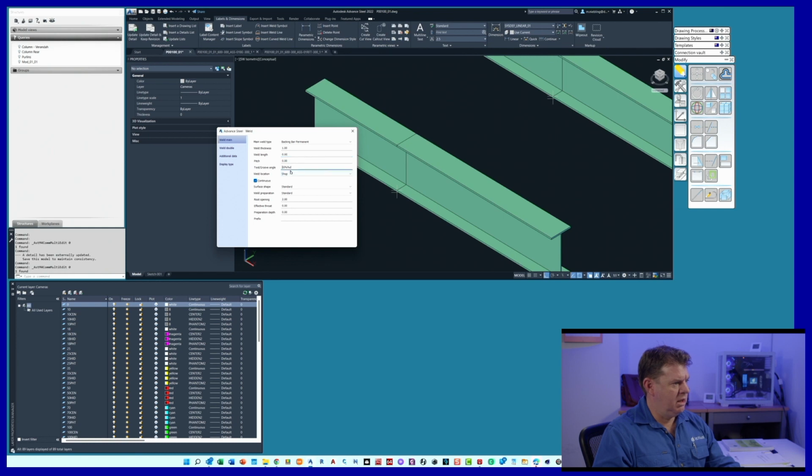Let's go. We'll do a double V, so we'll go 90 degrees. It'll be in the shop, continuous. We're going to go flat. Oh, we don't need that. So for this side, we'll go to 2. We'll go a V butt weld thickness of 10. Actually, we got that wrong. That should be 0 for that side of the weld.